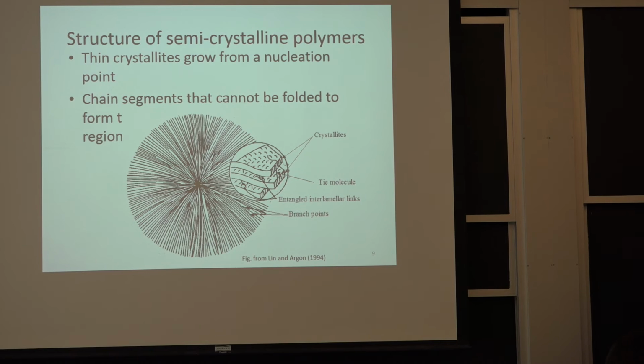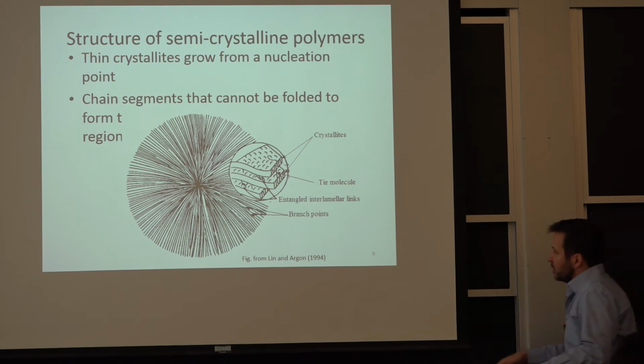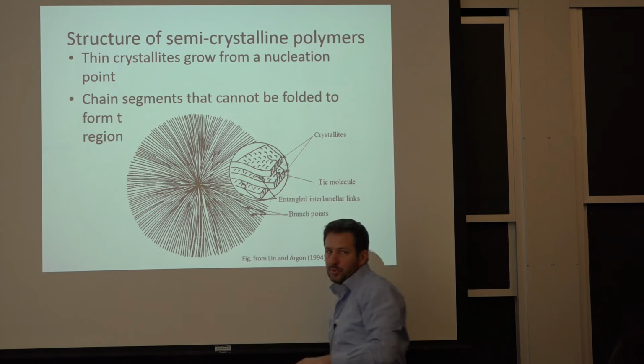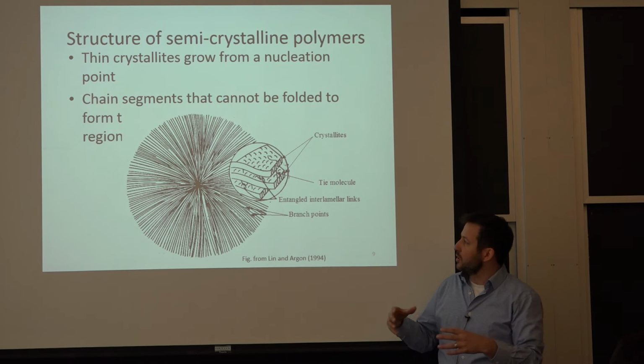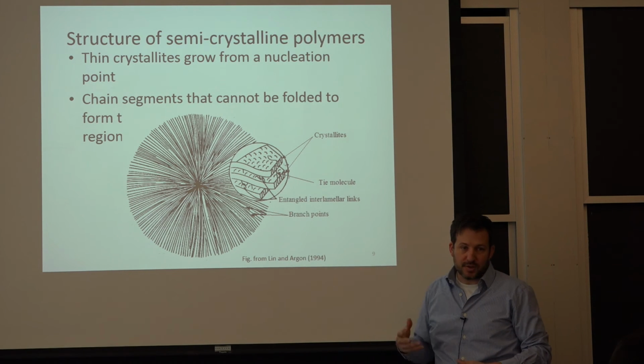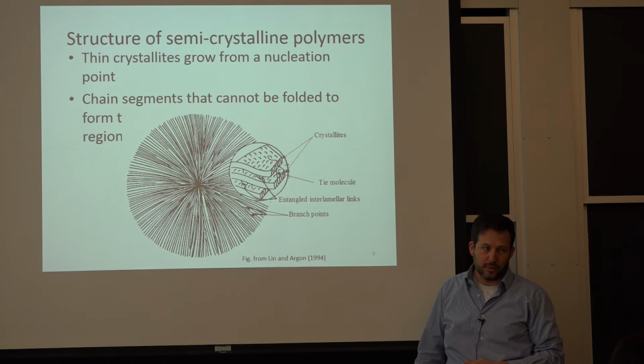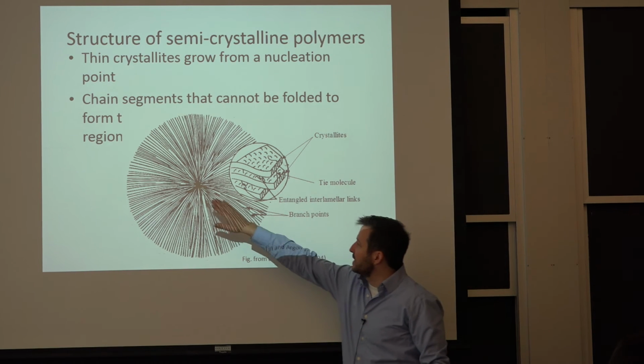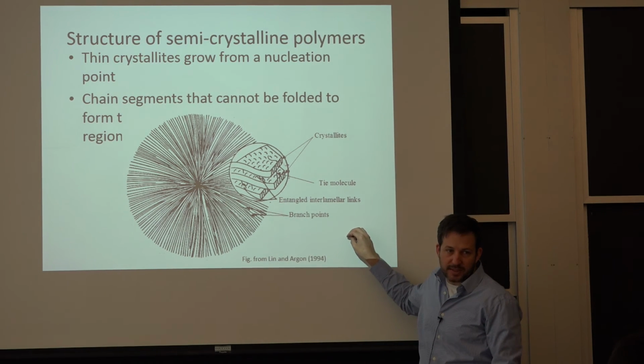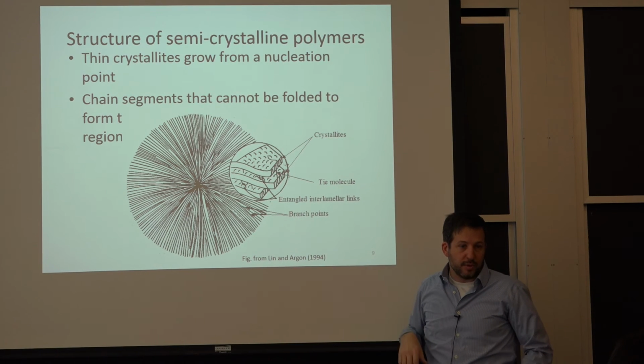If we were to cool it down very, very slowly, we get bigger crystals because we give ourselves more time for that organization. The spherulite is the overall organization, this whole thing that has hundreds and hundreds of crystals organized in such a way, and they connect to each other, just like the grains in the steel that we were looking at last time. Because as it's happening here, it's also happening on the next site, and eventually they get to each other.